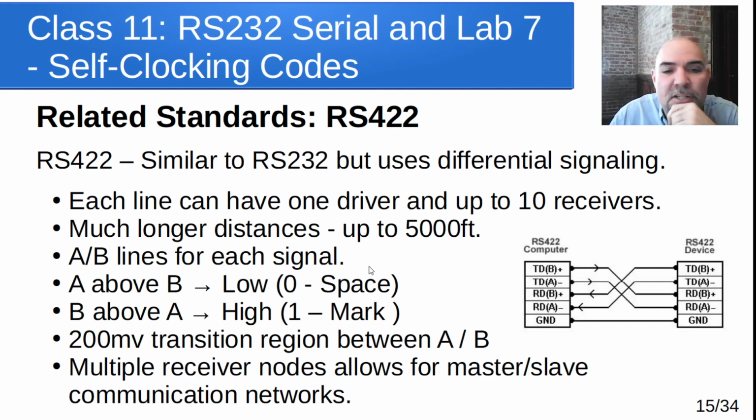The advantage is that you can actually have much longer distances, because what happens on those two wires is differential, meaning that one goes low, one goes high to send logic 0, and then to switch, they flip, and one goes high, the other one goes low. And so you can get distances that are much longer and much higher speeds. RS422 can also have one driver chip, one driver output, drive or communicate with up to 10 receivers that are listening to that. And some drivers can actually support more than 10 receivers, but the standard itself says one driver has to have at least 10 receivers it can talk to.